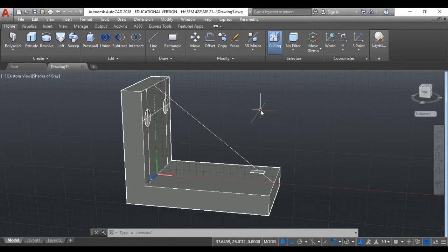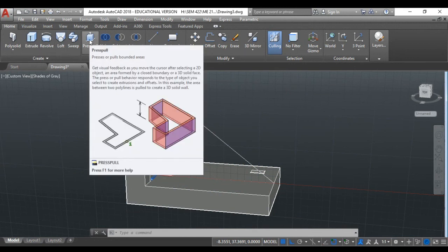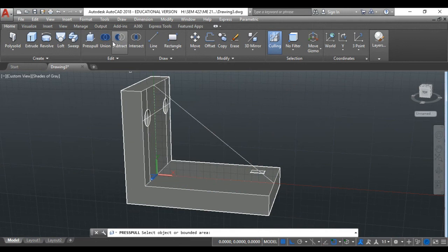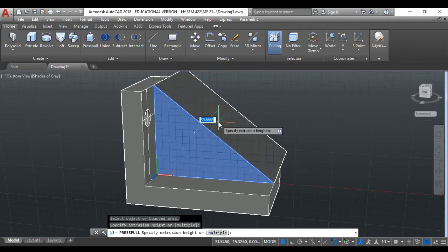If it does not work, I'm gonna show you the very last solution and the guaranteed solution, inshallah. But hopefully this one will help me out. Now I'm gonna go for, no, of course, not extrude. Why no extrude? Because this triangle was drawn with 3 separate lines. Remember this all the time, guys. So better to go for press pull, and then alhamdulillah it works.